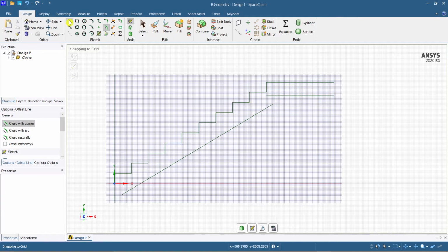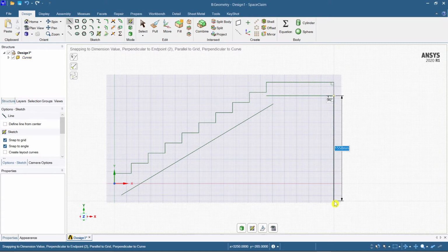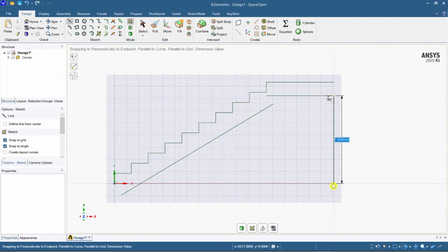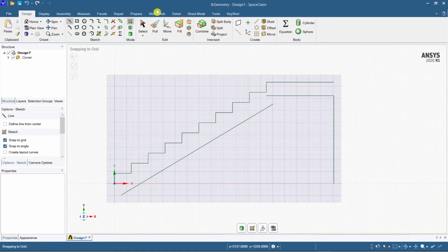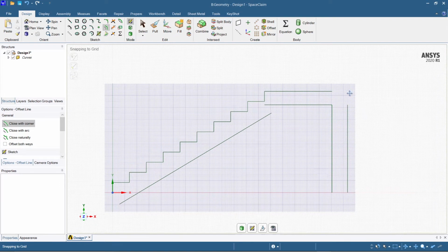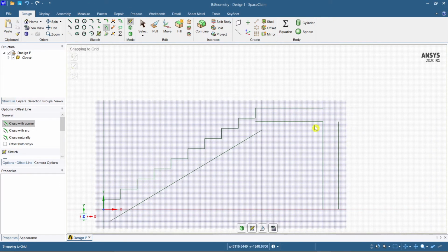Actually, again you will have a line here. Actually I have a wall here, so let me create a wall with the ground level. This is my ground level. Let me create a wall at this level. Then I'll take an offset. My wall is 230 mm in thickness. So 230 mm thickness. This is fine.